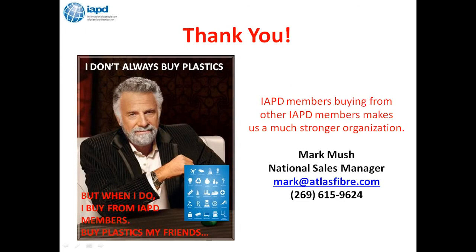They say that they've run into color variances with the laminates. The mill spec is vague, giving a broad range of what is acceptable. What is your advice in advising customers on the color variation? There is absolutely no chance you are ever going to get a color match in any of the laminates. That's my advice. They are not a decorative product. They're an industrial product, and unfortunately, even from the same mill, different lots may wind up with different shades, different colors. Not dramatically from the same mill, but you will get variation. And from mill to mill, you will get wide variations.